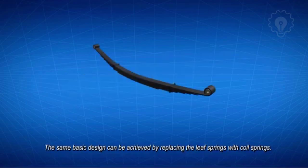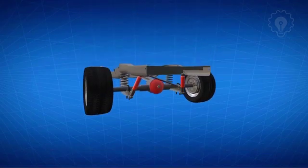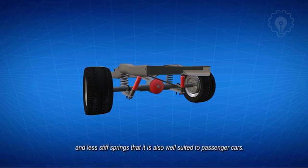The same basic design can be achieved by replacing the leaf springs with coil springs. The coil spring and shock absorber can be mounted as separate components or as a single unit. Unlike the leaf spring suspension for load-carrying vehicles, a solid axle coil spring suspension has reduced unsprung weight and less stiff springs, so it is also well suited to passenger cars.